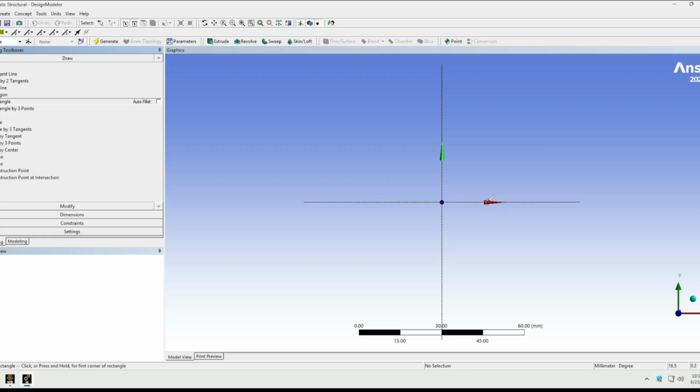The C option that you see pops up means that we are on a specific axis or line. So we are going to start from 0, 0 and then create our rectangle. Again, you see the scale is given to you down here. Obviously, we want the rectangle to be 200 millimeters by 20 millimeters.